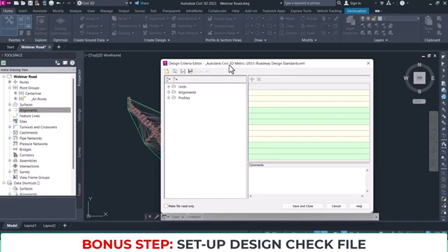All right, so you can modify this into your country's codes and then save it into Civil3D. Okay, that's the simple thing to do. So look at under units, we have metric, whatever. So this is just a normal unit. Okay, if you are using metric system, which is for Nigeria, we're using metric system. So you leave all these ones by default here, unless there's a need to change them, but here is where you make the changes.